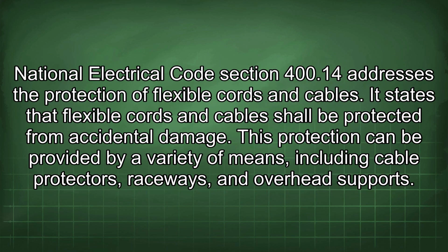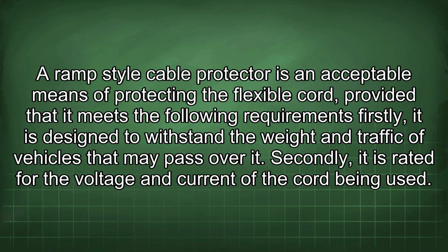National Electrical Code Section 400.14 addresses the protection of flexible cords and cables. It states that flexible cords and cables shall be protected from accidental damage. This protection can be provided by a variety of means, including cable protectors, raceways, and overhead supports. A ramp-style cable protector is an acceptable means of protecting the flexible cord, provided that it meets the following requirements.